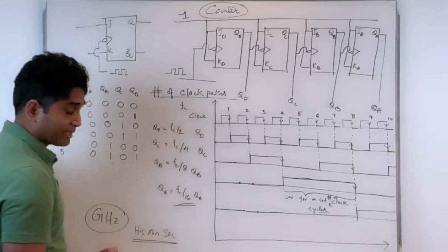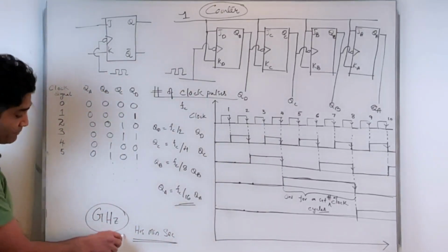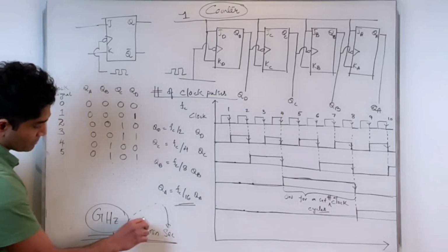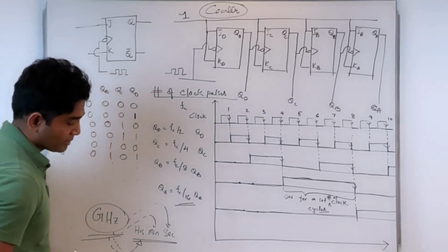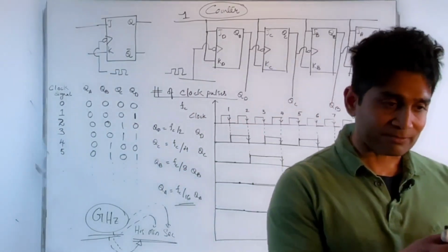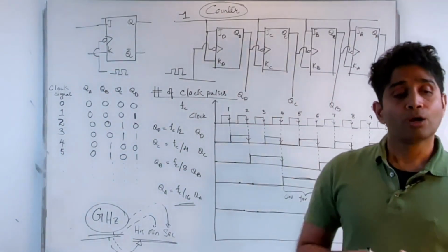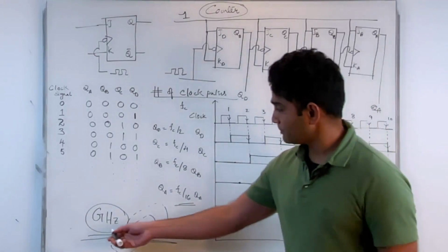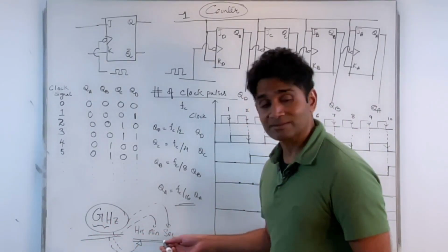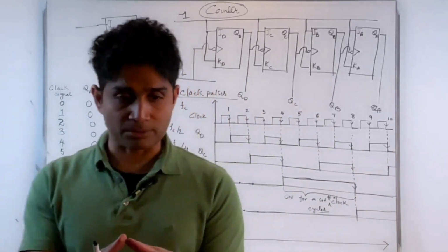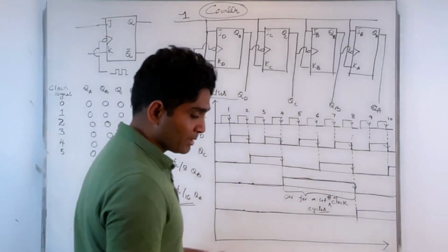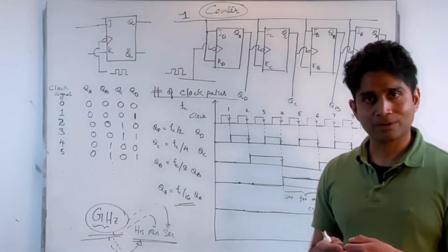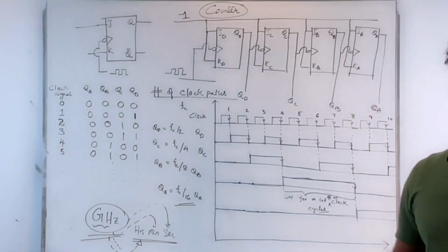That means I need to count down. In other words, I need to divide the frequency so that I can get the seconds, minutes, and hours count from your master clock, right? So you need some kind of frequency division, and you can figure out by what factor I should divide my clock frequency to be able to count hours, minutes, and seconds. That's how your computer is able to display time and count forward in time, right? Using your master clock as the signal.